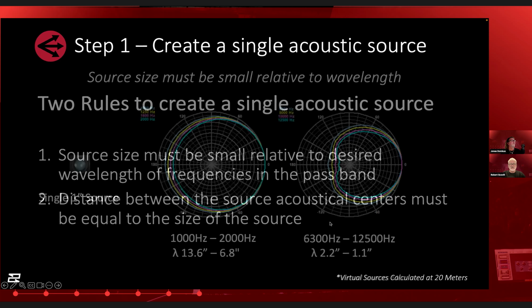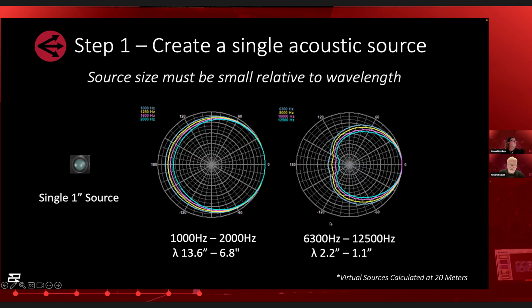So let's go down this a little bit. Let's just look at a 1-inch driver. This is just a raw 1-inch driver. And as predicted, you can see I've got a range from 1,000 hertz out to 12,500 hertz shown here. And it is omnidirectional, as you would expect, for the most part.